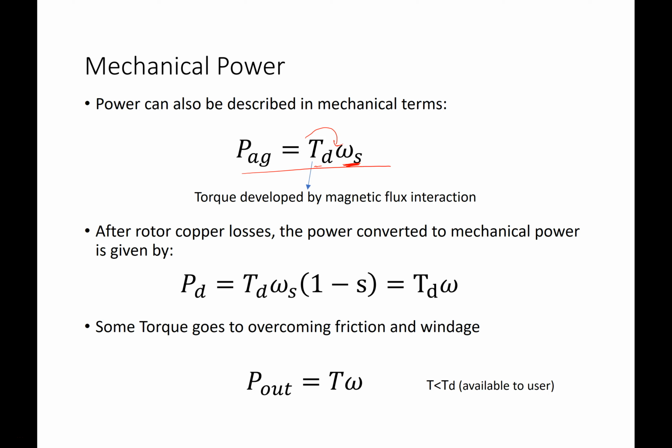So it's not that it will always be 60 Hertz. Depending on the number of poles of the machine, this could change, because the larger the number of poles, the slower the magnetic field will turn, because the more north poles and south poles you'll have in a single revolution. And if you're not sure what I'm talking about, you could go back to the initial video and look at the part about number of poles and how the magnetic flux distribution is derived.